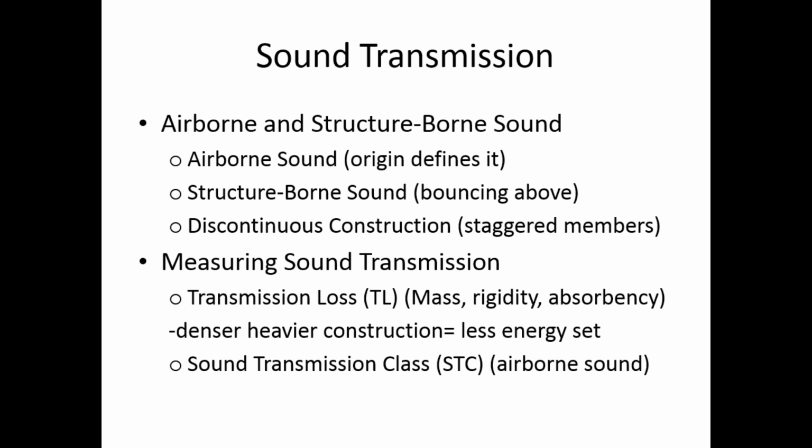If we stagger those, then we're adding this point of dulling amidst that sound plenum where the board is separating the plenum just a little bit by adding the extra stud. By staggering them, they're not all in a row, so there's not a wider expanse between studs, and it's creating a way for the sound to stop, more so than when we have them further apart in larger expanses, all running up and down vertically.